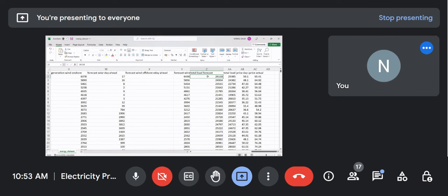What does this mean, total load forecast, sir? What do you think? This is the estimated load that you are expecting consumers will be buying. There are two parts of the load: one is variable, another is fixed. Similarly, in case of generation, there are variable and fixed sources. Solar and wind are the variable ones. These keep fluctuating highly, whereas other generation will not fluctuate highly.